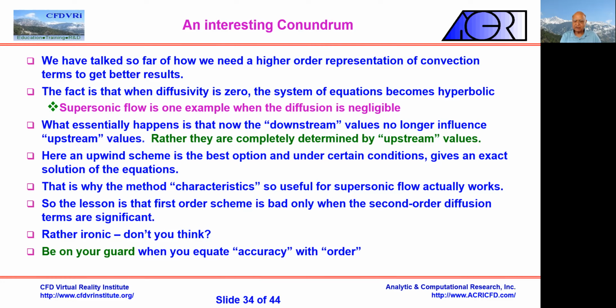What two things you should trust: do your grid independent study, and compute the order of accuracy if it's very time expensive to obtain solutions, right? And check the residuals of physical quantities like fluxes, the amount you have and how much you should have, and where the deficit is. Those are the real tests in real life, not residuals, not discrete equations. You are an engineer. Physics, never forget the physics. Physics doesn't forget you.